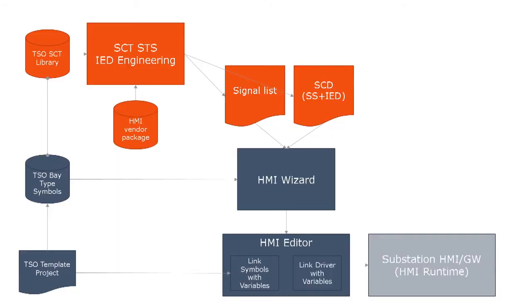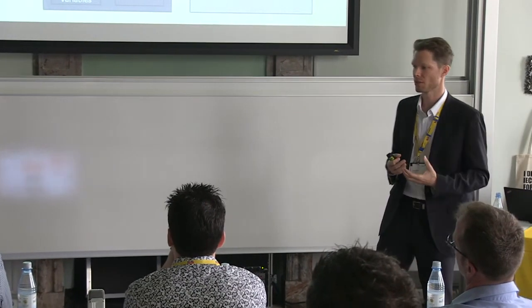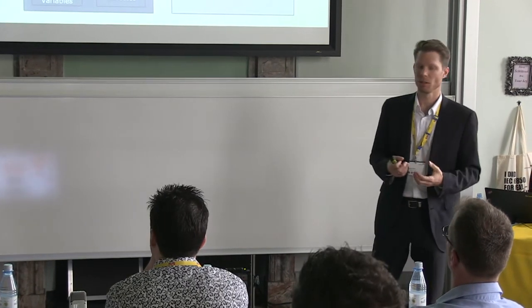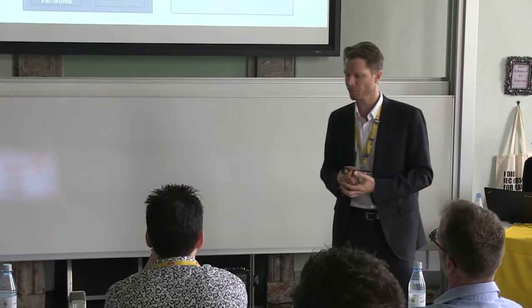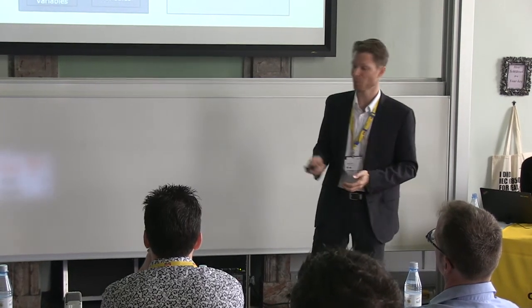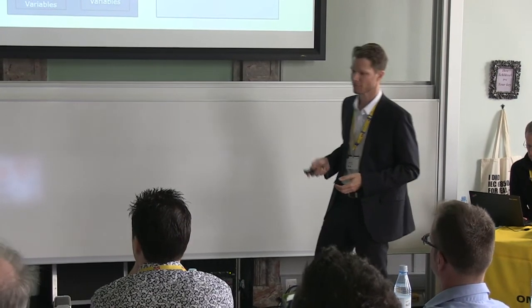And this HMI wizard then generates all the necessary stuff in the HMI tool, in the HMI editor, which then, when you start it, starts this runtime, starts the driver, starts communicating with the 61850 servers, with SNMP maybe, starts the gateway maybe, and yeah, should work as it was described here and here or here.